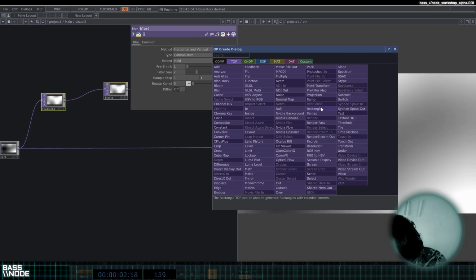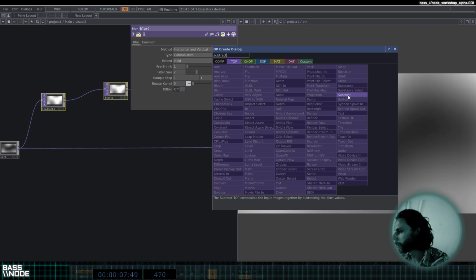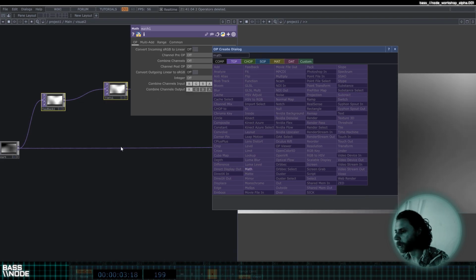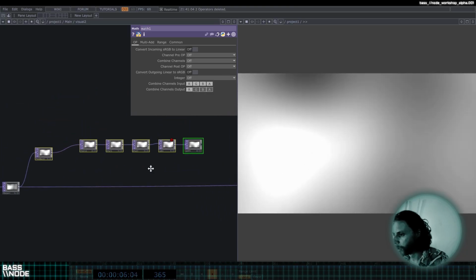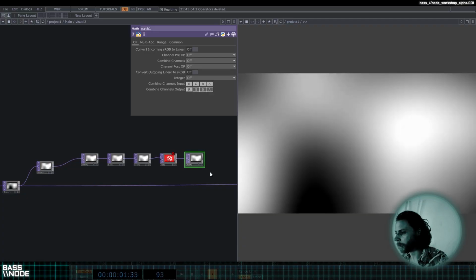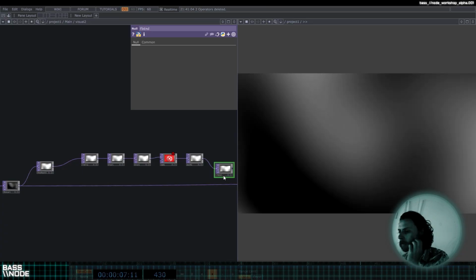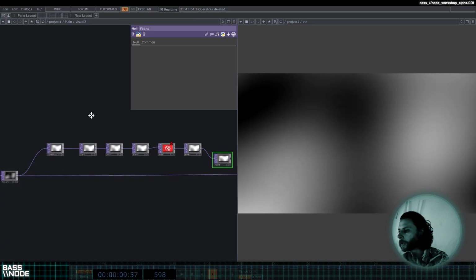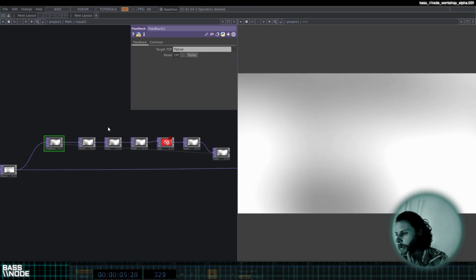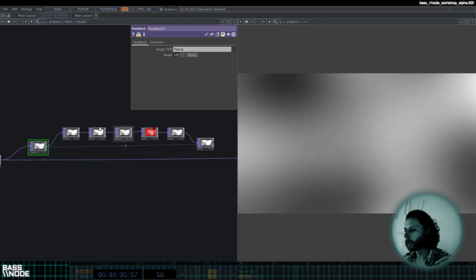We're gonna try to find our subtract. If you're struggling, you can always type in to find it and it'll still work with our shift. And then we're gonna add a math, and then we're gonna click out, and now we have the basis for our feedback loop. And then I'm just gonna add a null at the end and call this feedback end, FB end. And to make the feedback loop actually feed back on itself, we have to drag and drop this onto feedback, and it should update automatically. Nothing really is gonna happen because we need to modify our chain a bit.